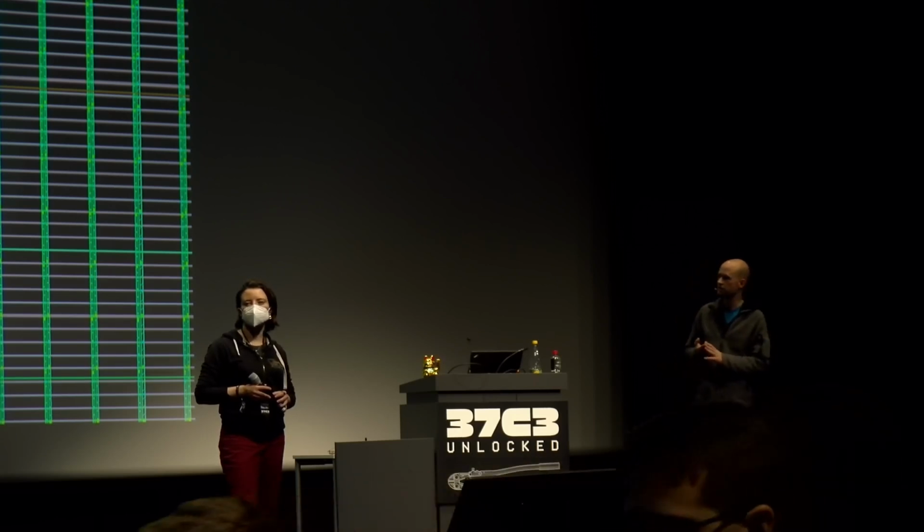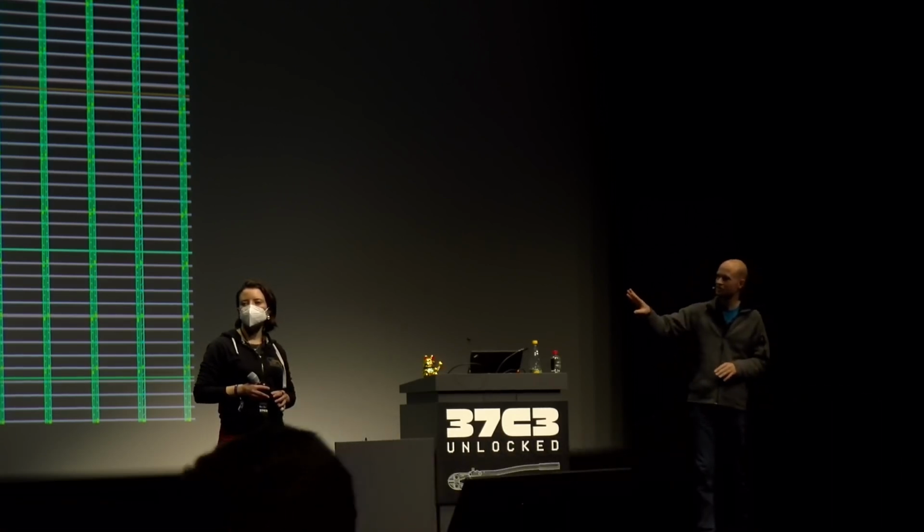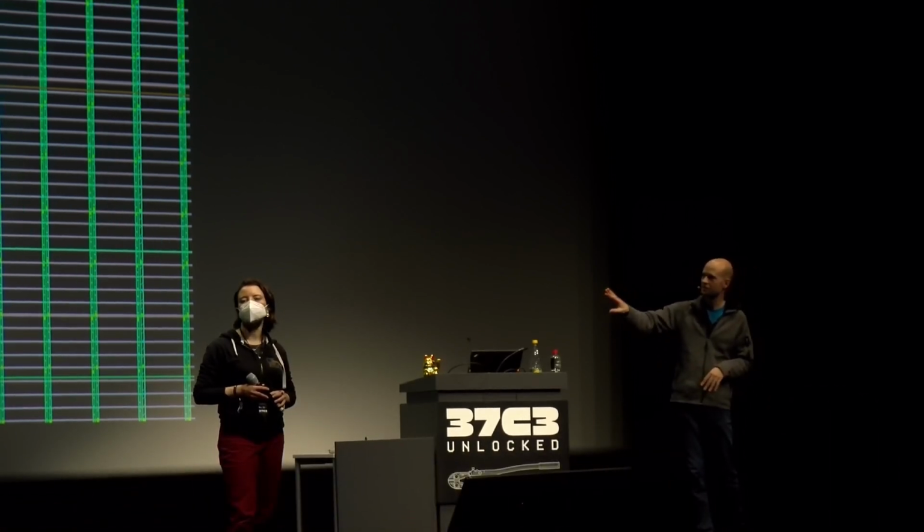There are also other things on the left that we now don't see, like the pins or pads. It could be that shifting this whole blob towards there, even though we make those lines a bit longer, still minimizes the wire length because there's more wires going to the other side. But ultimately, we are trying to minimize the wire length to reduce timing latency. That is what we are trying to do.